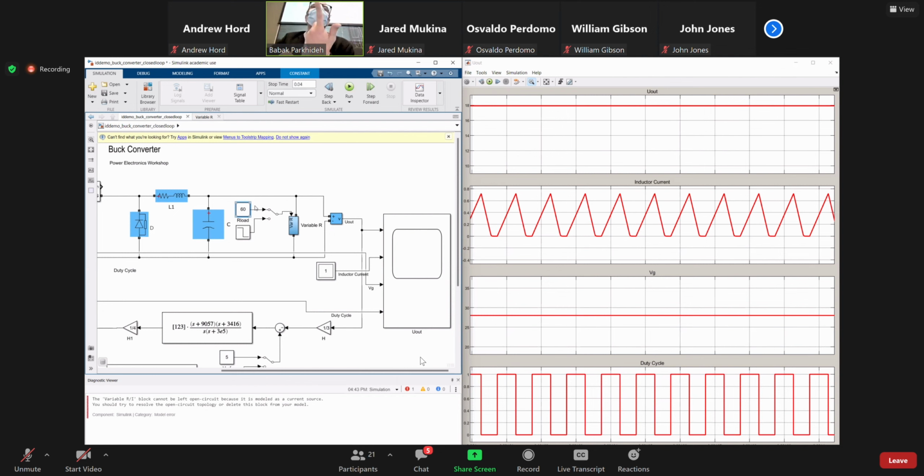Okay, what are the other advantages? What is the design parameter that gives you, as a designer, the ability to operate this converter in a DCM? What components may be affected by this? So let me put it this way. Do you need a bigger inductor or a smaller inductor to have a higher probability to operate in DCM? In other words, if you want to operate the converter in DCM, do you need bigger or smaller inductors?